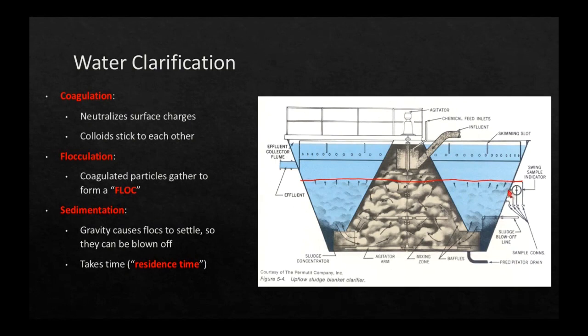Well, we've got these 4 lines here, and these 4 lines are going to sample the sludge at various points. Now this very top one probably will give us clear water. If we start to see sludge coming out of that top sample line, then we know that we're running the bed too high. We'll talk shortly about what we need to do to get the bed where it's supposed to be.